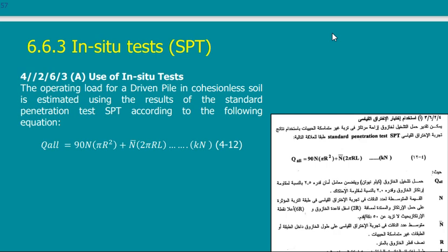Now I design a pile and I tell you that this pile can carry 200 tons. Okay, you will design everything, calculate the dimensions, make the drawings, give it to the contractor. The contractor will go to the site, and before he starts, I will tell him, you have to perform a pile load test at the beginning.